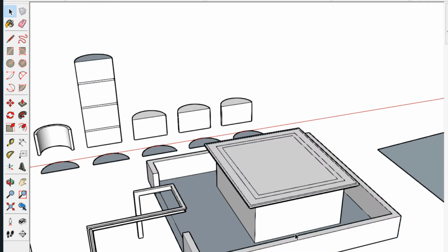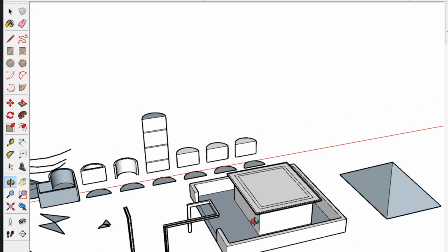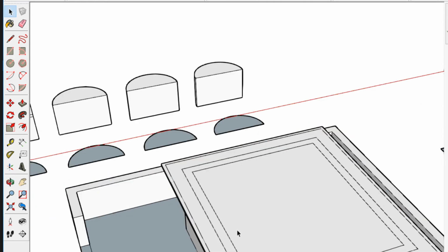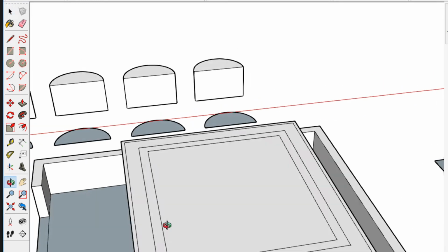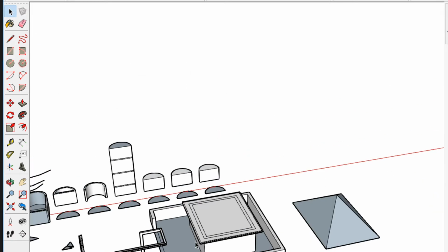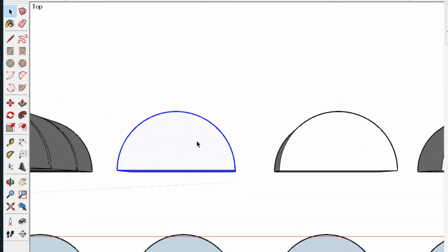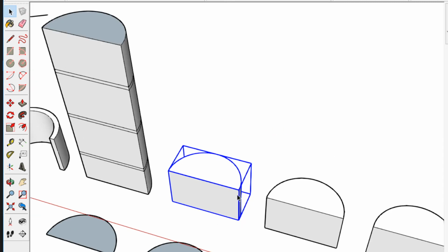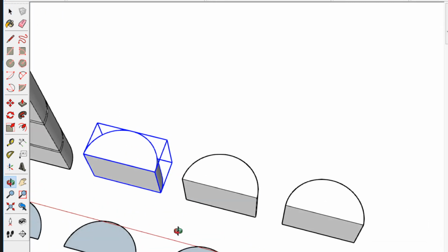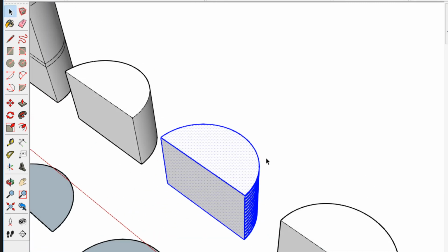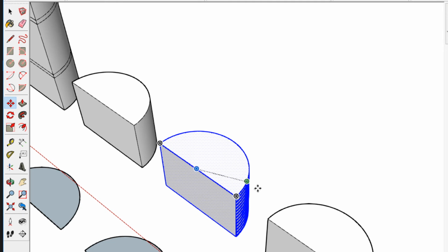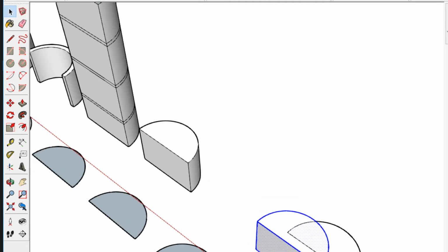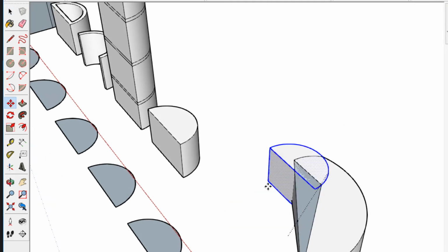which many of you are doing, but I actually group them, which many of you are also doing. So how do you group something? This thing, I triple click, right click, make group. For my shortcut, I just press G. So what does a group do? When this thing coincides with this thing, they get glued.